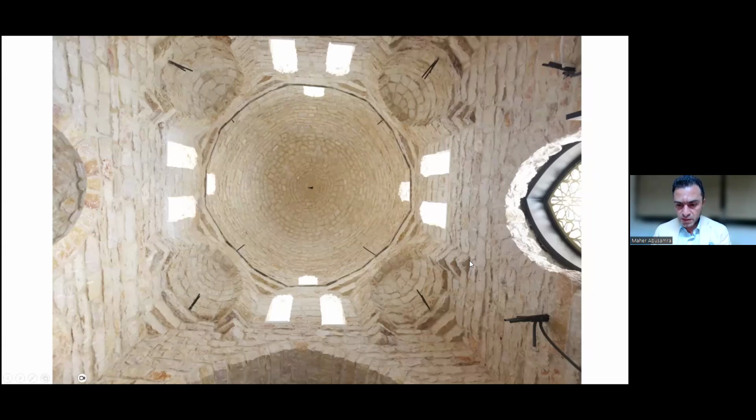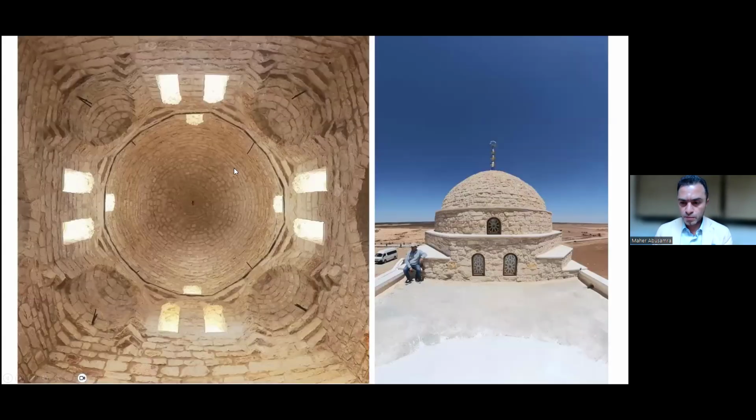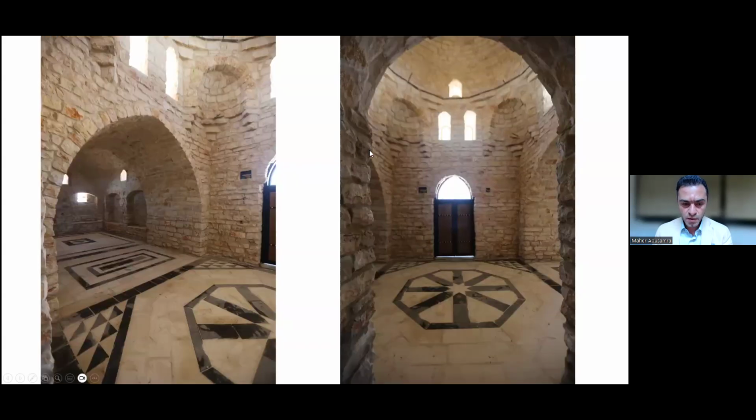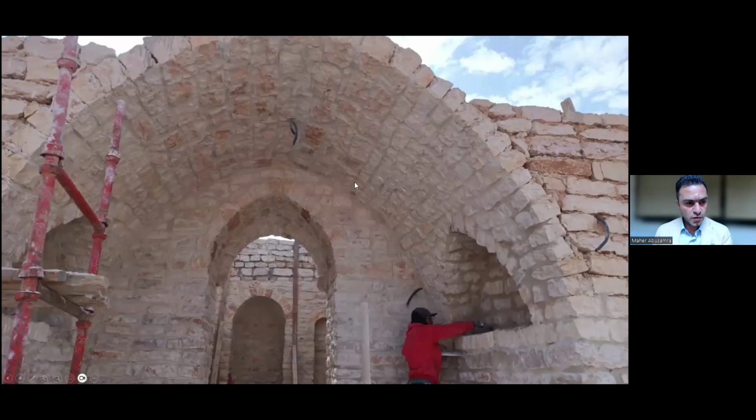Here you can see how we start from the square on the plan with those three levels to carry the squinch. Also here in the middle, like 3 steps, twin windows, another 2 steps to convert the octagon to a 16-sided polygon. Then we have another 4 windows and rotate the dome. This is the dome from outside, from the roof. Interior shots during the construction.